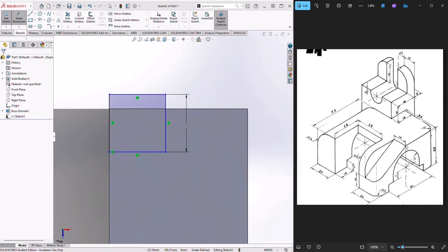And this line is actually in the middle or in the mid distance between these two parts over here. So the 6.5 millimeters represent the radius of this section here. To find the exact width of this section, we'll need a 10 plus 2 times 6.5 or 13 and another 10 over there. So 10, 13 and 10, which is 33.